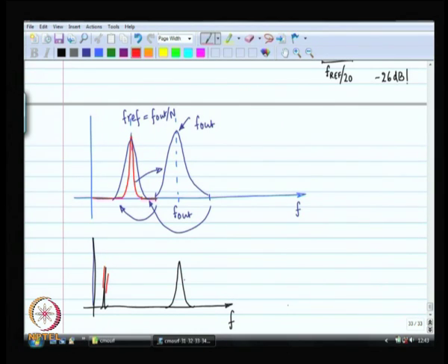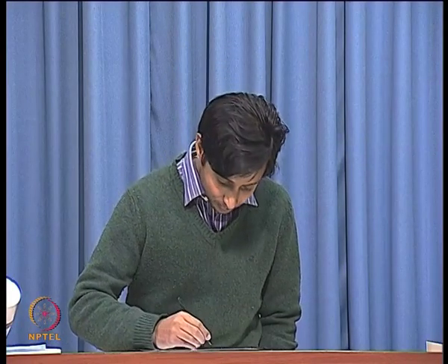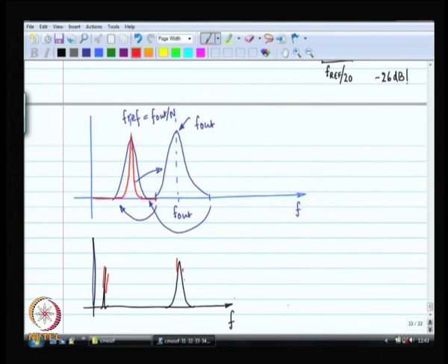That is the strange part, right, that the loop bandwidth is only that much. So, within that loop bandwidth, the output is going to mimic the reference, and outside that loop bandwidth, it is going to behave exactly as if it were the normal VCO.